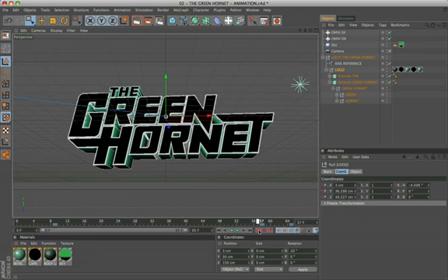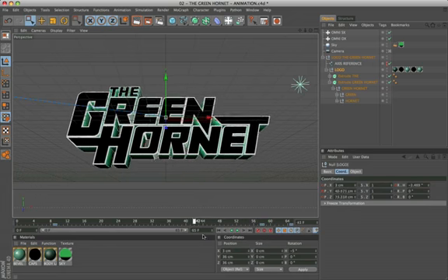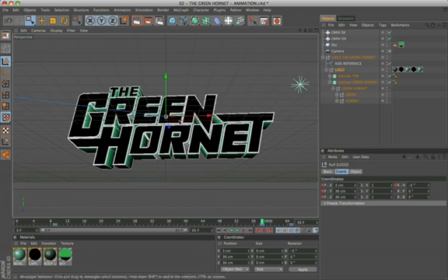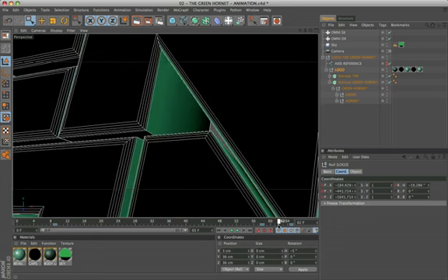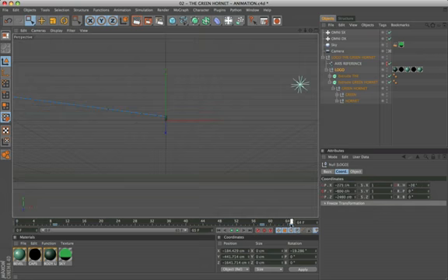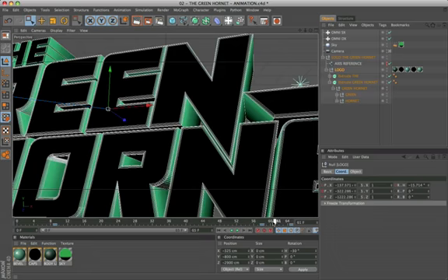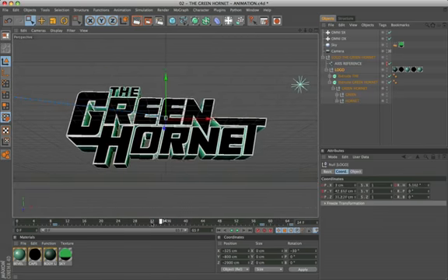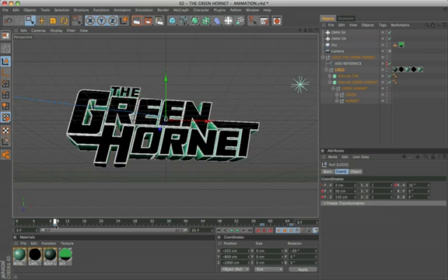This animation sequence is completed in frame 58, with the values x, 3, y and z, 36, and rotation P to -5 degrees. This is the middle animation. Finally we have a fast fly out of the logo to the camera, with the following values: x, -325, y, -800, z, -2009, and P rotation, -30 degrees.